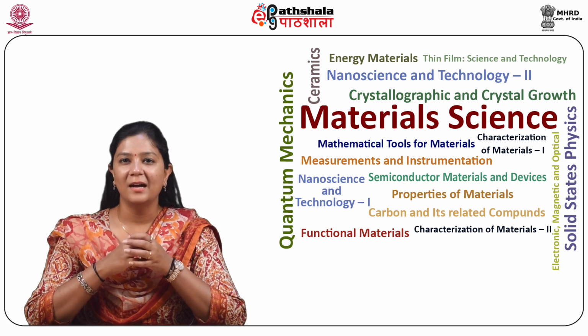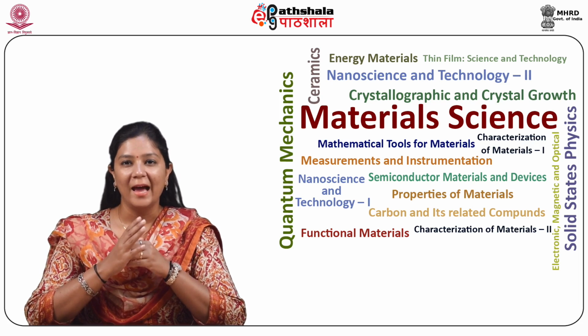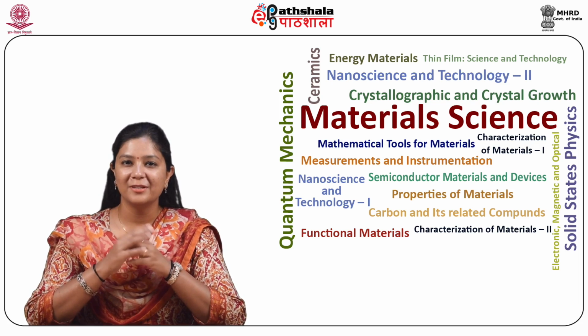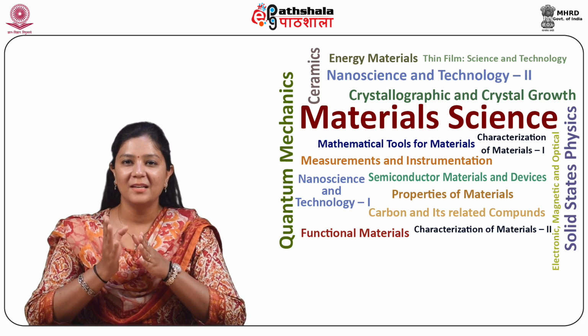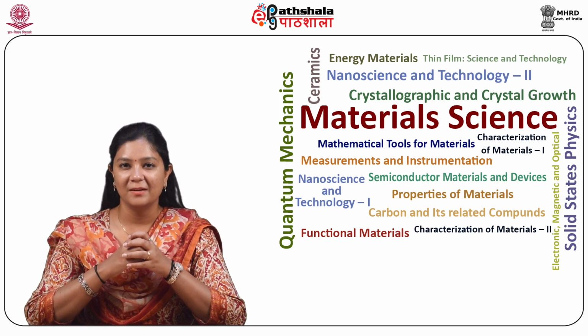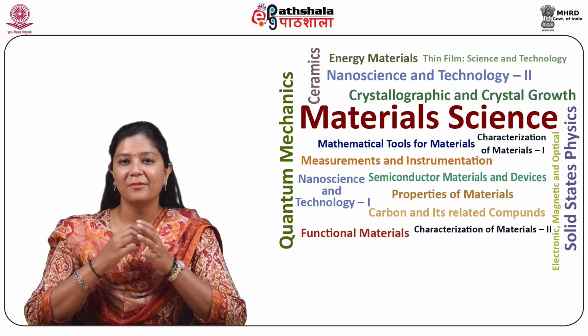These perovskites are unique in that they exhibit high electronic conductivity and resist reduction under exposure to syngases at high temperatures. At 1000 degrees Celsius, the conductivities of these materials range from 1 to 30 Siemens per centimeter, with activation energy of 12 to 19 kilojoules per mole. Depending on dopant and dopant level, lanthanum chromite based interconnects have been shown to be stable in cells for as much as 69,000 hours.